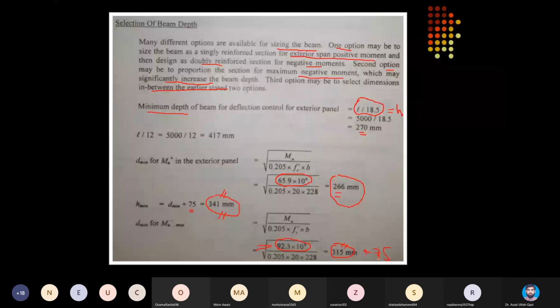However, for section 2 and 4, it is quite possible that your neutral axis depth will be in the flange, because I'm talking about the section AA, which in my picture are 4 or 5.